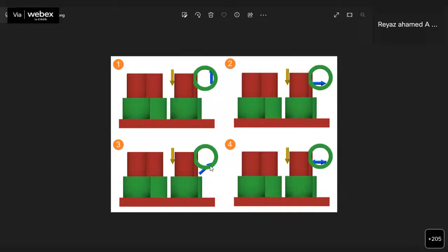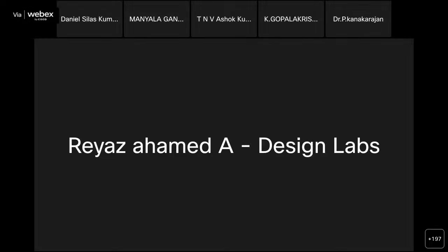For that we gave the load value on both Y and Z. And this one may act as a torsional effect, so we gave the load value in both directions, one side in the negative direction and the other side in the positive direction. These are the loading conditions we have applied so far.